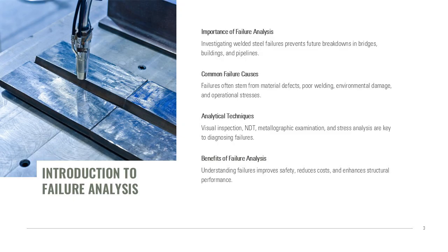Failure analysis of welded constructional steel components is a critical process in structural engineering and metallurgy. It involves investigating the causes of failure in welded joints and components to prevent future occurrences. Welded steel structures are widely used in bridges, buildings, pipelines, and industrial machinery, making their integrity essential for safety and reliability. Failure analysis helps identify root causes such as material defects, improper welding techniques, environmental factors, and operational stresses.